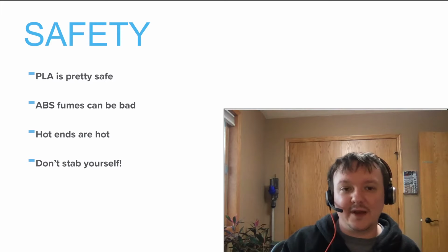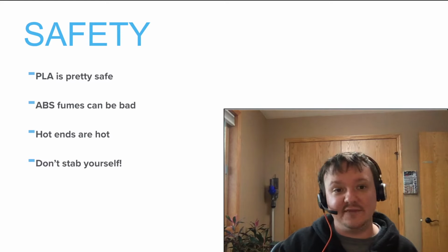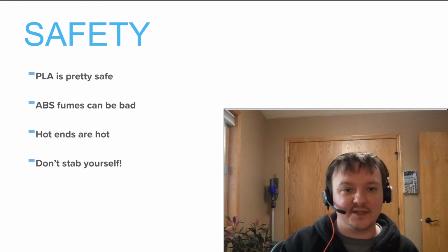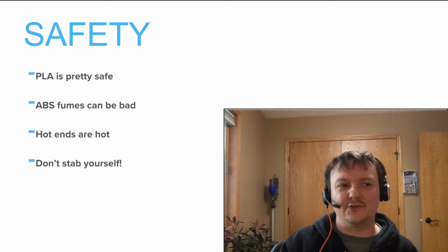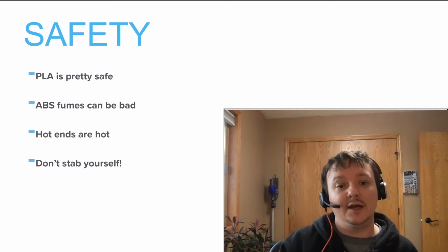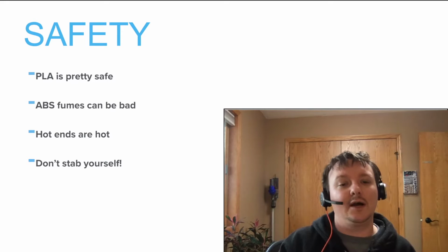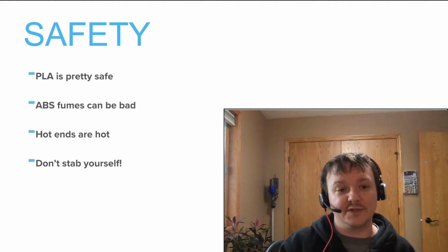I wanted to give a quick callout to safety. PLA is really safe. You wouldn't want to inject yourself with it, but there's not really any fumes. It doesn't smell bad. ABS fumes can be very, very bad. You want to stay away from those. Hot ends are very hot. They're usually about 230 degrees centigrade. That's more than hot enough to boil water, and it's more than hot enough to burn yourself.